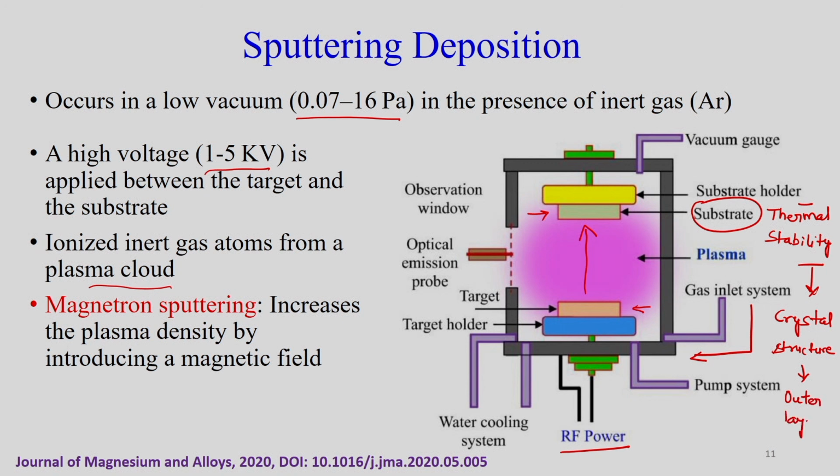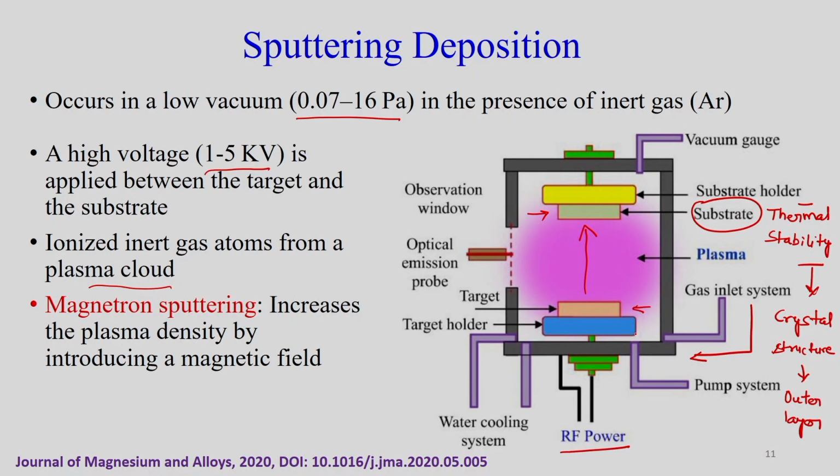So, these are a few challenges, namely what the temperature should be, because you have to reach a temperature to vaporize your target, and the target is a solid. Typically it requires a high temperature to form the plasma cloud, or evaporate the solid, in order to get it deposited on your substrate.